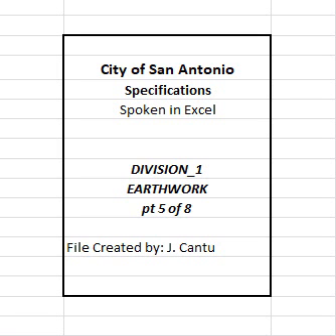Cut and remove all exposed reinforcing steel from the broken concrete. Move the material dumped in piles or windrows by blading or by similar methods and incorporate it into uniform layers. Feather edge or mix abutting layers of dissimilar material for at least 100 feet to ensure there are no abrupt changes in the material. Break down clods or lumps of material and mix embankment until a uniform material is attained. Apply water free of industrial wastes and other objectionable matter to achieve the uniform moisture content specified for compaction.